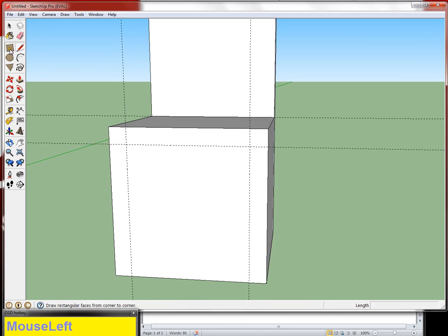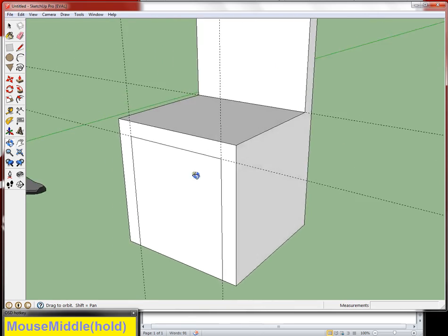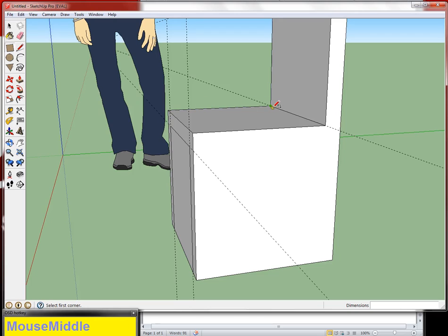So I'm going to grab the rectangle tool in order to make this rectangle here. Again, I'm going to pay attention to the intersection marker, and down here on the intersection marker. Now, the reason that's important is because up here, it looks like these 2 lines intersect, but they don't. And I can tell that because SketchUp is telling me that they don't intersect. If they intersected, SketchUp would tell me that there's an intersection going on, right, like that, right there. But it doesn't, because they don't touch each other. They look like they overlap, but they don't, because that other line I made is way in the back.